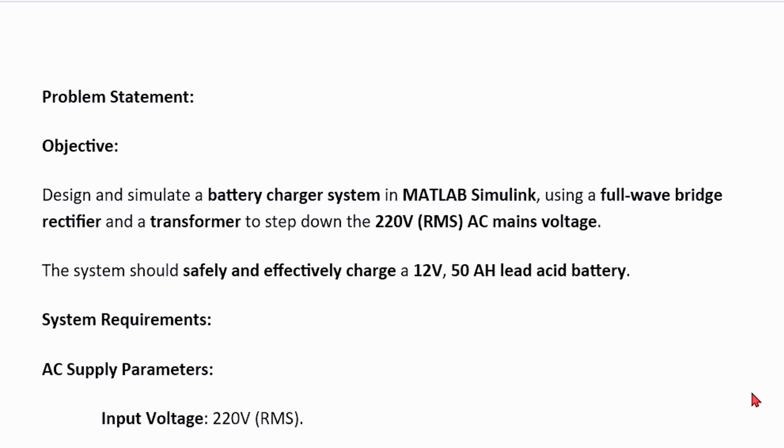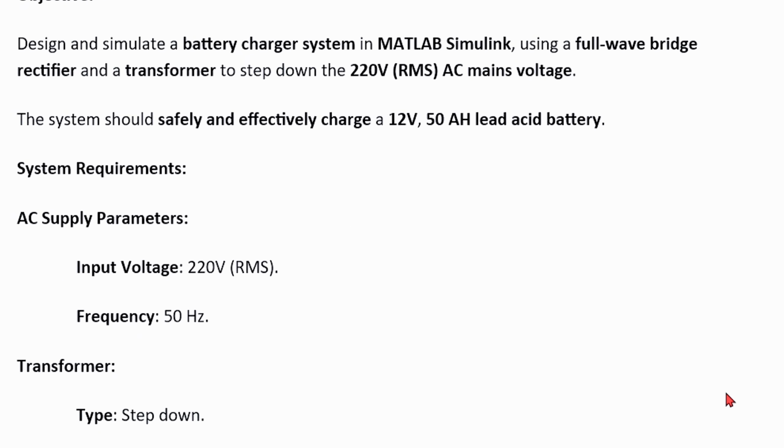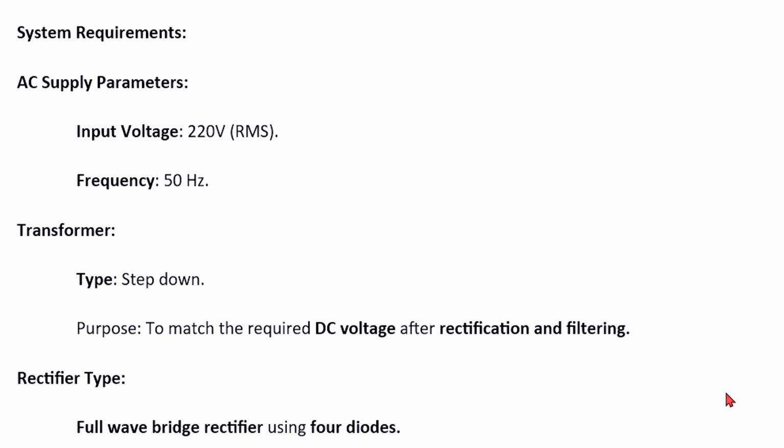Problem statement. Objective: design and simulate a battery charger system in MATLAB Simulink, using a full-wave bridge rectifier and a transformer to step down the 220 volts RMS AC mains voltage. The system should safely and effectively charge a 12 volts, 50 ampere hours lead-acid battery.